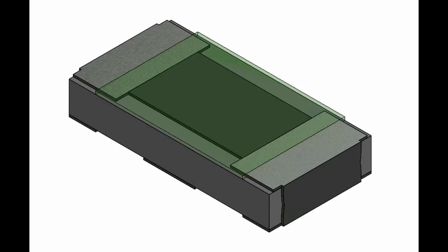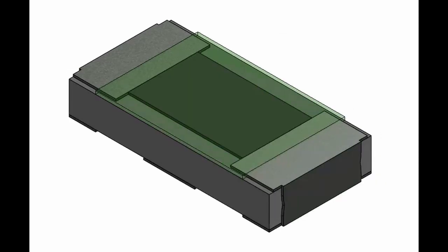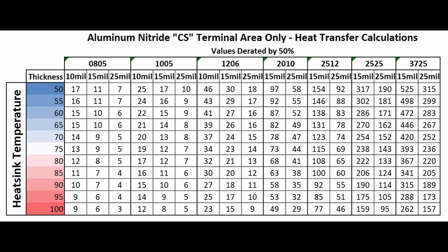IMS routinely produces parts that have an electrically isolated center strip designed for sinking heat directly downward to a ground or thermal layer using plugged vias. In the case of a pulsed resistor, we can think of no better way of managing the onslaught of rapid and sometimes damaging thermal transients.